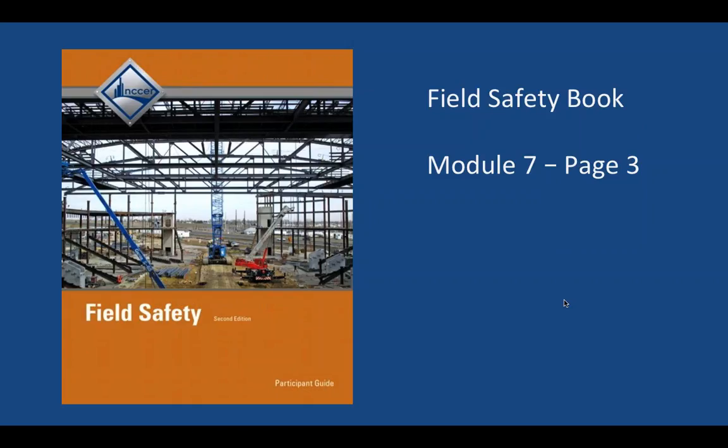Like I said, we got through page 7. We wrapped up on communication. And then if you look at page 8, we had left off last week on the operator's daily checklist. And there's just an example of an operator's daily checklist. You'll notice that this is for a crane checklist, or heavy equipment. It shows all the guards, the devices, looking for any type of leaks, looking for condition of tires or tracks. So there's a checklist for everybody, just in case you want to check it out.